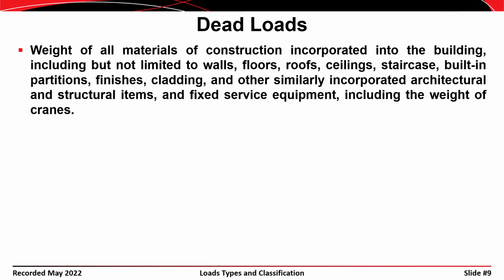Okay. Dead loads include basically all of the self-weight of the structure. That's not just the weight of the structure itself, but also the weight of the non-structural elements, including ceilings, built-in partitions, finishes, cladding, etc. Now, the partition load is a little bit different.